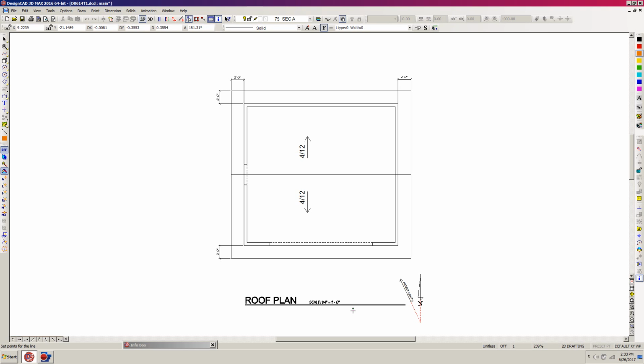I'm going to hit the H key, which toggles on the orthogonal mode so I can get a nice straight line and go up a ways, and then this left click to set another point. And I'm hitting my scroll button to activate command. You can see my section line right here.